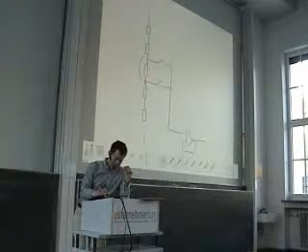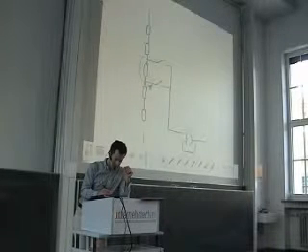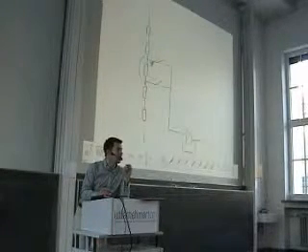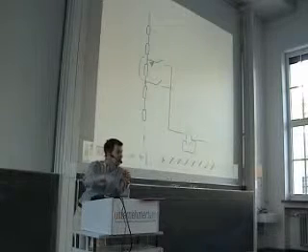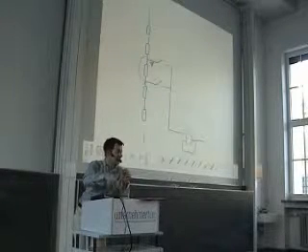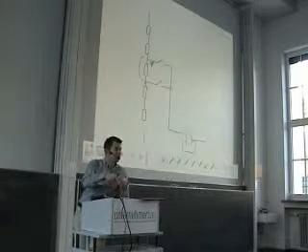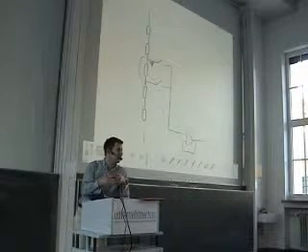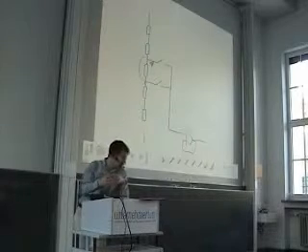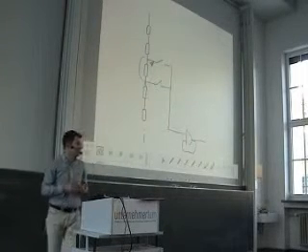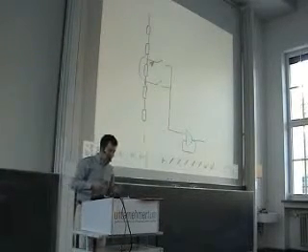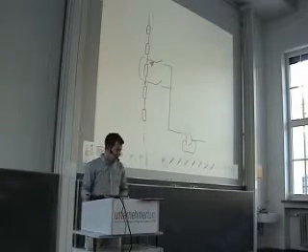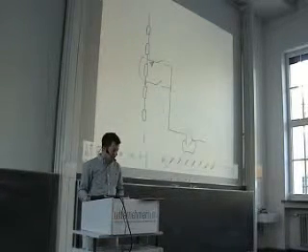Then the voltage going from this switch position to this switch position is the same, but it can never go down. This cannot happen here. So the big advantage of the resistor string structures is that they are inherently monotonic. Always, if you have binary weighted structures, you have the situation that this non-monotonic behavior can occur.